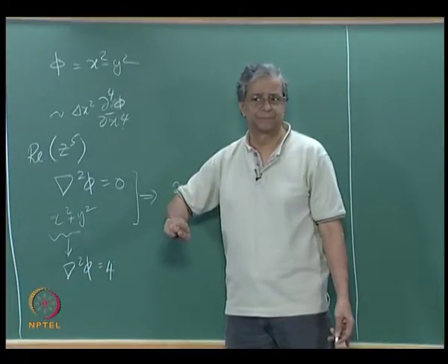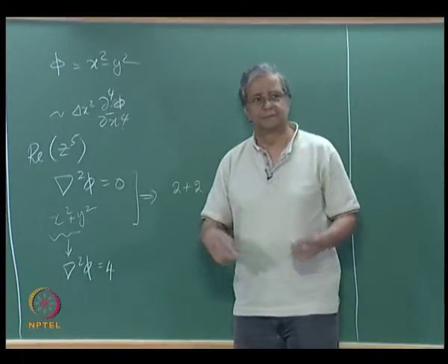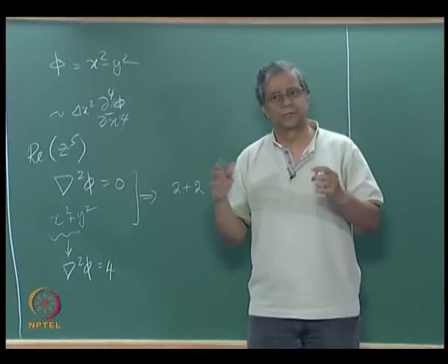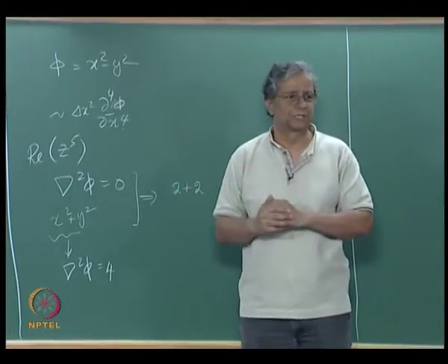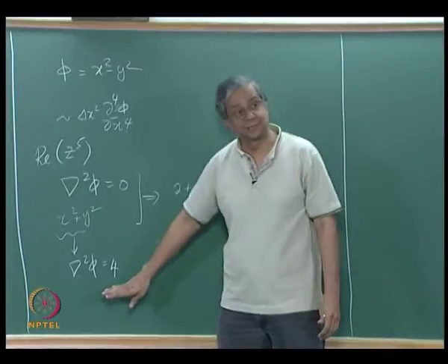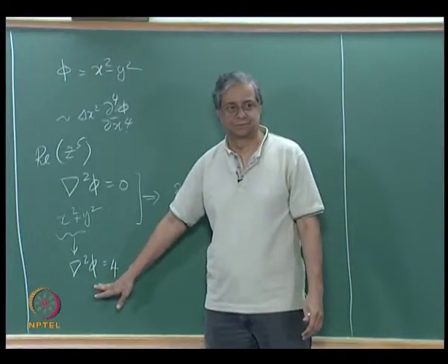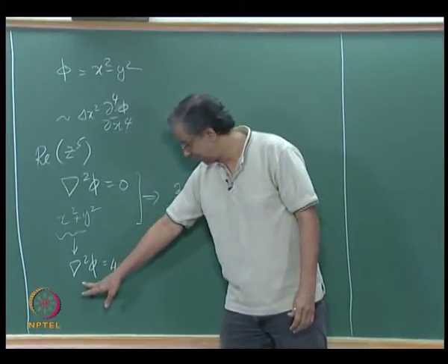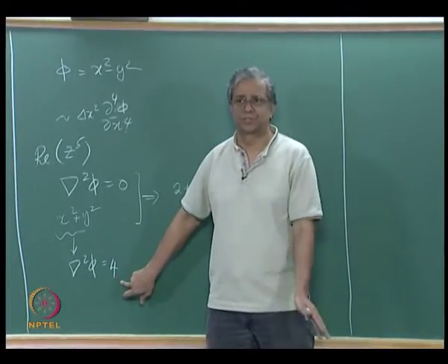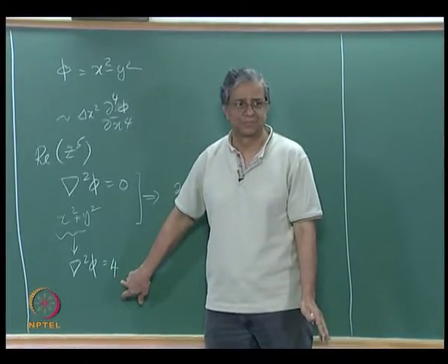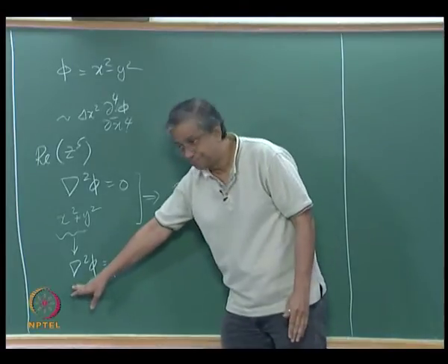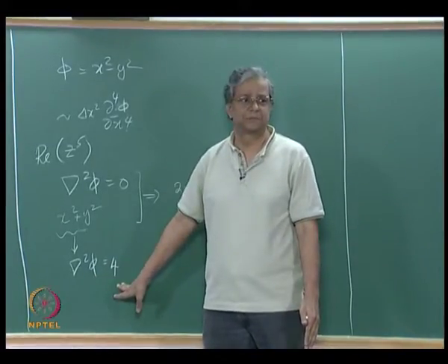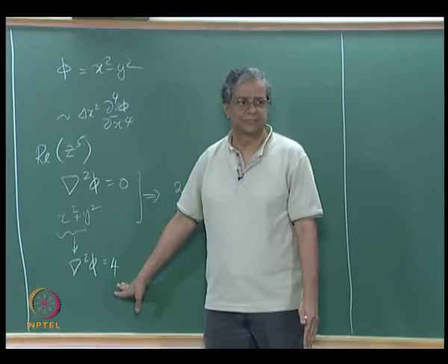Is that clear? Okay, because very often you will hear people saying, oh, I am going to compare it to experiment because I do not have a solution, I am going to compare it to the solution of another code because I do not have a solution. Not necessary, right. You can generate an equation that is very close for which you have a solution. What it will do is it will add typically a source term that has its own consequences, as long as you are aware of that, but basically you can turn around and generate an equation for which you have a solution. Is that fine?